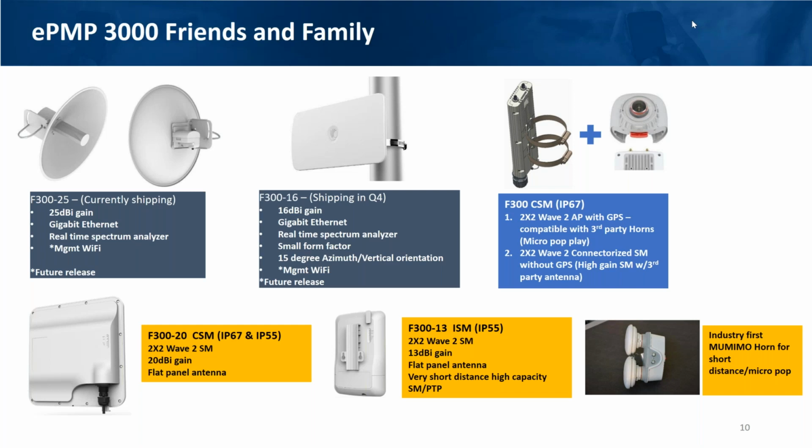So within a 90-degree sector, this antenna covers a 70-degree chunk with the highest gain possible. You want to put your subscribers within that 70-degree beam width. That's how you're going to get coverage. Yes, you may have a guy or two on the side lobes, maybe up close, and that's all okay.